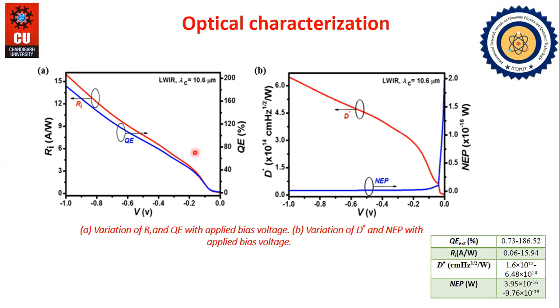This more than 100% efficiency is due to the combined effect of the hot carrier multiplication effect, external bias voltage, a high electric field across the heterojunction, and a significant potential barrier in the conduction band.